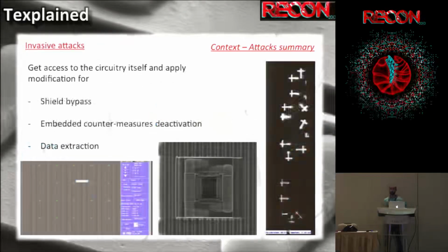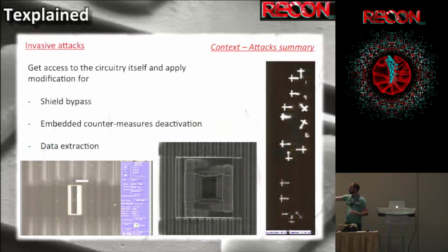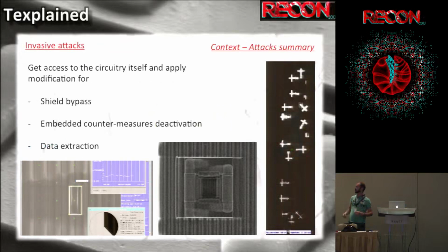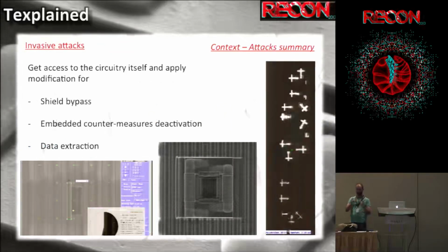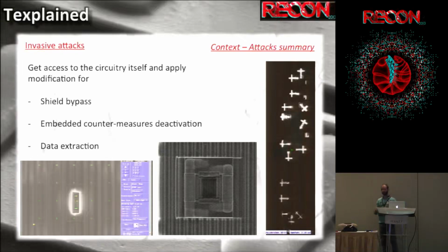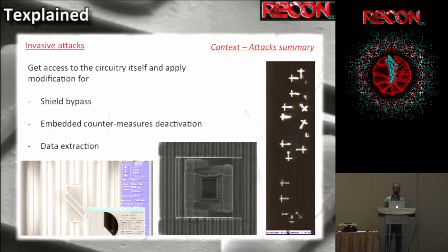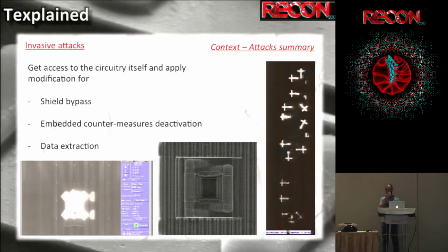For example, on this slide, we can see 3 different pictures. In the first one, I want to contact a line at layer -1. So I go in between the 2 lines that are on the top, and I contact my line and make a pad. And then I can just connect to the pad and do whatever I want.